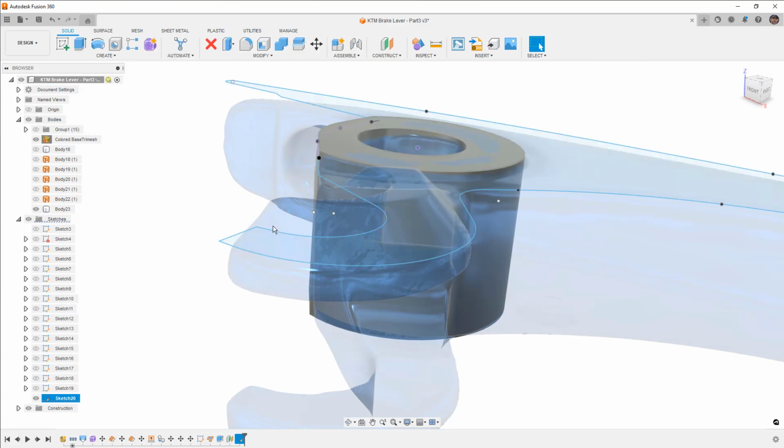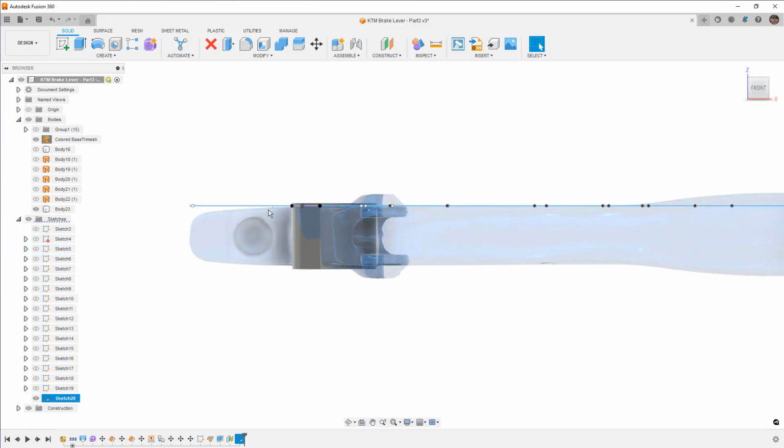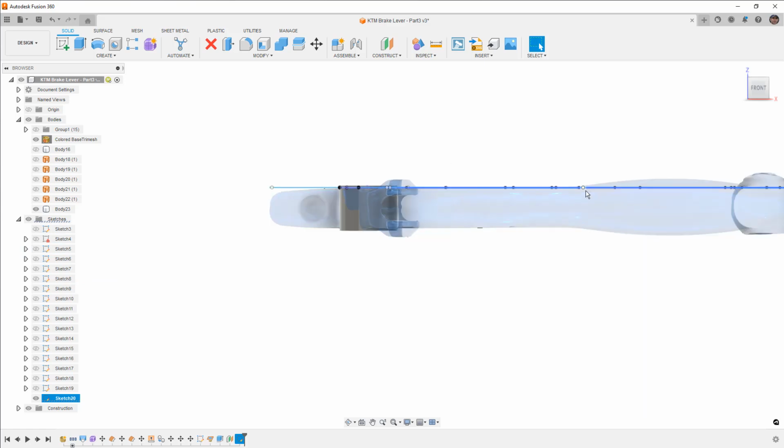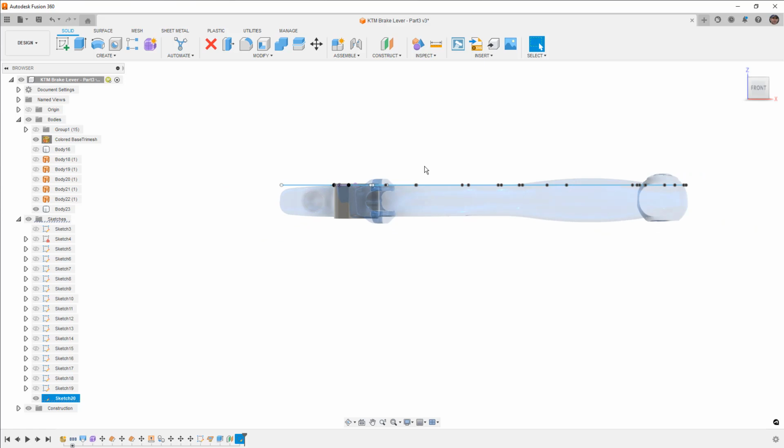And now we've got something that we can extrude. Now, remember when we're looking at the front view, we need to have geometry above our sketch plane. You can also see that this sort of tapers down here. So this means that we need to extrude this up and down past the point where we actually need the geometry. This is the reason why we're not going to be building these little hook pieces just yet, because we're going to have to trim this from the side.